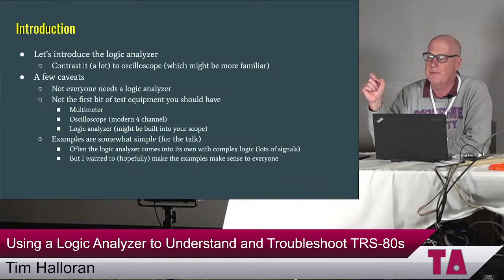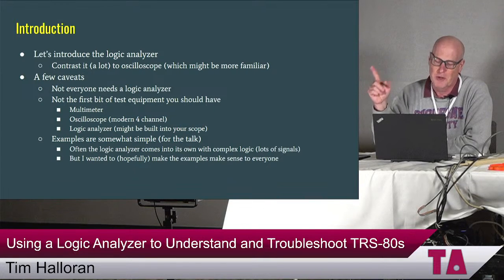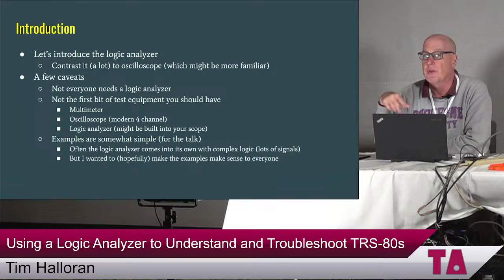It's definitely not the first bit of test equipment you should have if you're trying to fix computers. First off, a good multimeter is probably a worthwhile investment. And then you definitely want an oscilloscope before you have a logic analyzer. Logic analyzers these days can also be built into oscilloscopes. I'll be demonstrating that quite a bit, and that's really convenient as well.